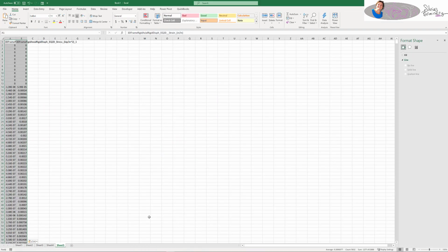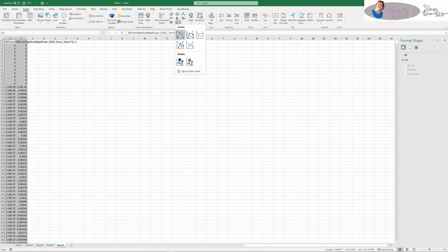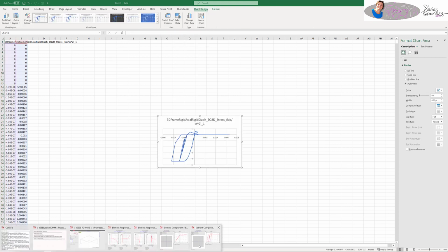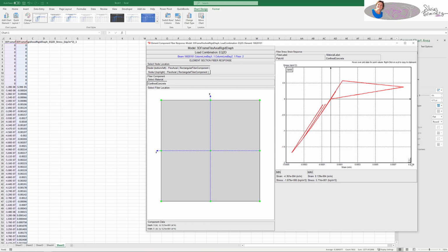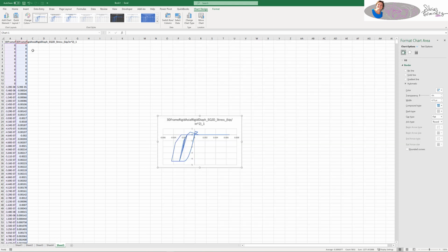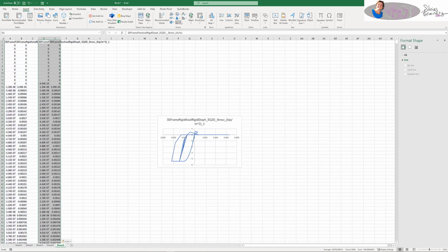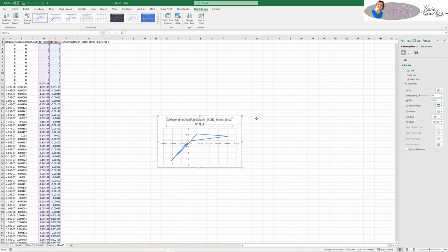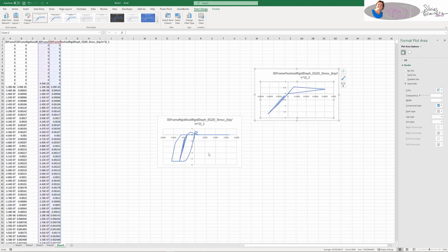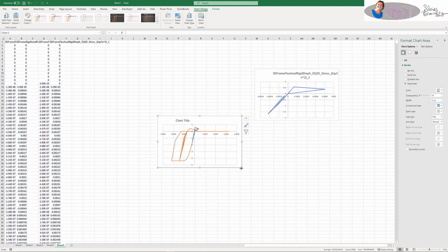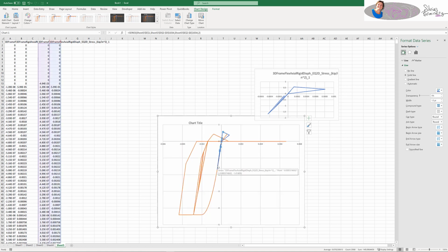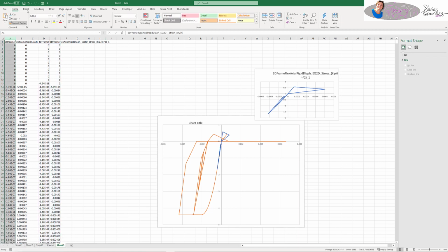It just never quite goes into enough compression for the concrete. You see it there, the concrete doesn't go into enough compression, it stays a lot in tension, and then it really limits the forces that it can resist, because remember, you've got concrete on both sides of your section. So this is really good evidence, showing the response in the 2 cases.